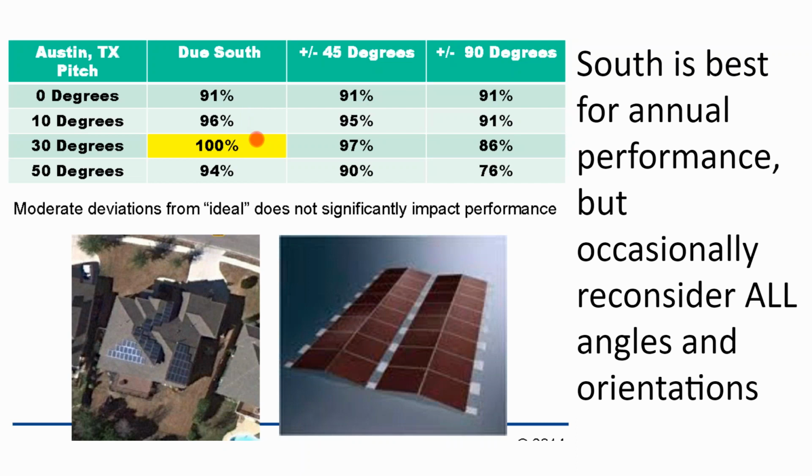And so what that means is on a rooftop that's already slanted and already tilted, it's just not a good idea to tilt up off the roof. Just stay coplanar to the roof. It's the best structurally for the roof. It's the best for wind load, some structural and mechanical issues. It's also the cheapest and the easiest to install. And then, when you tilt up off the roof, you have to worry about inter-row shading, which is difficult to model at the very least.